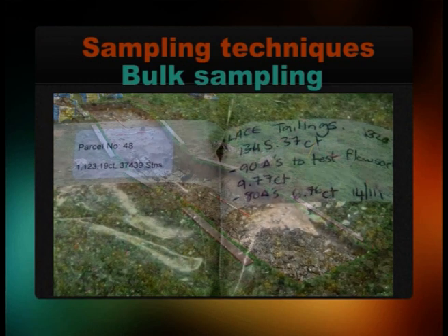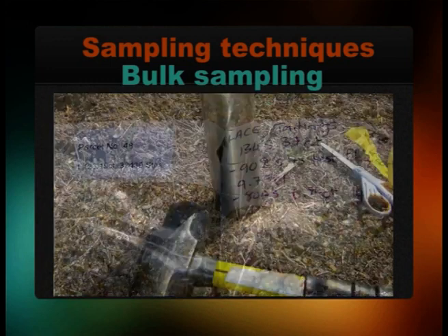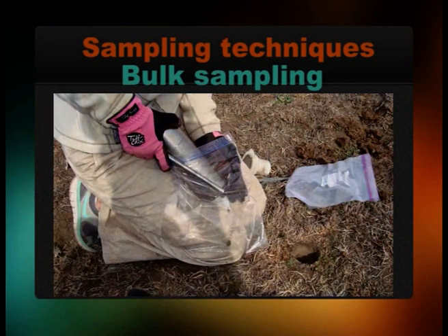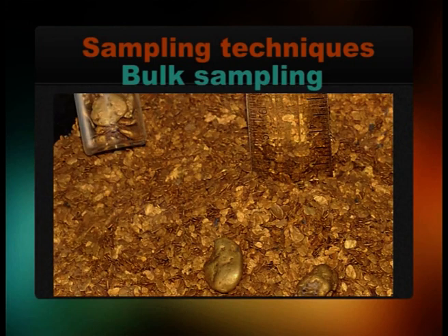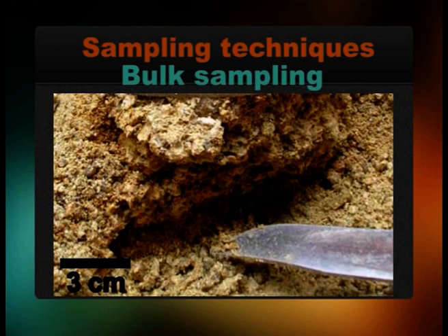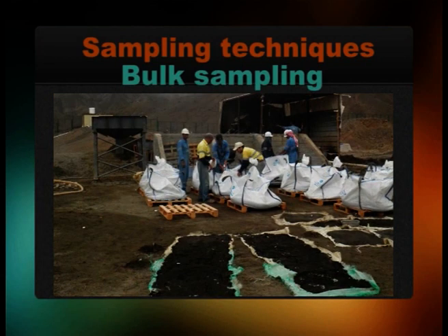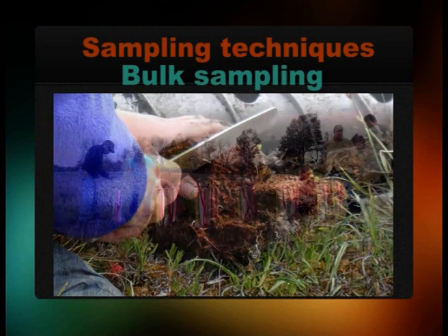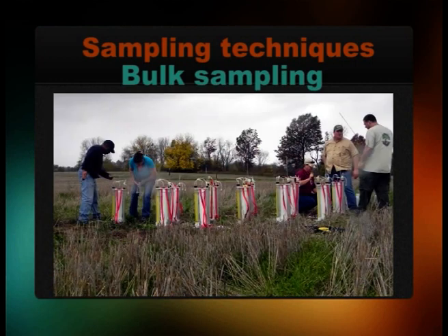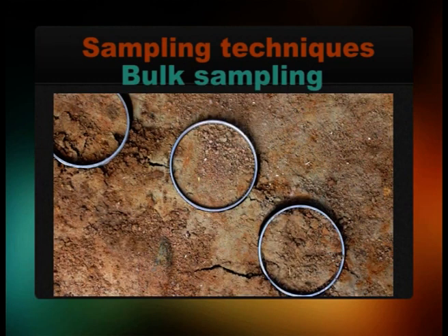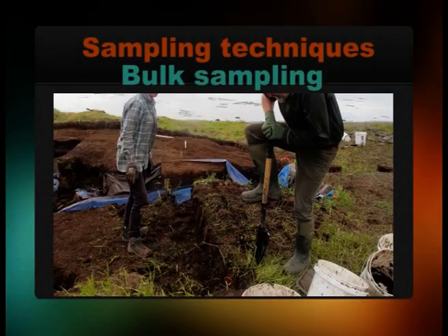Often the bulk sample will be a composite of material from development drifts and raises. Ideally, drift, round or other portions should be selected from geological mapping and prior sampling, handled separately, and should be stored temporarily on a pad for sampling if not directly processed. The bulk sample will consist of these components and will take into account the geological continuities. The appropriateness of the bulk sample will be related to its source, to the variability of the deposit, to the deposit morphology, and to anticipated problems.